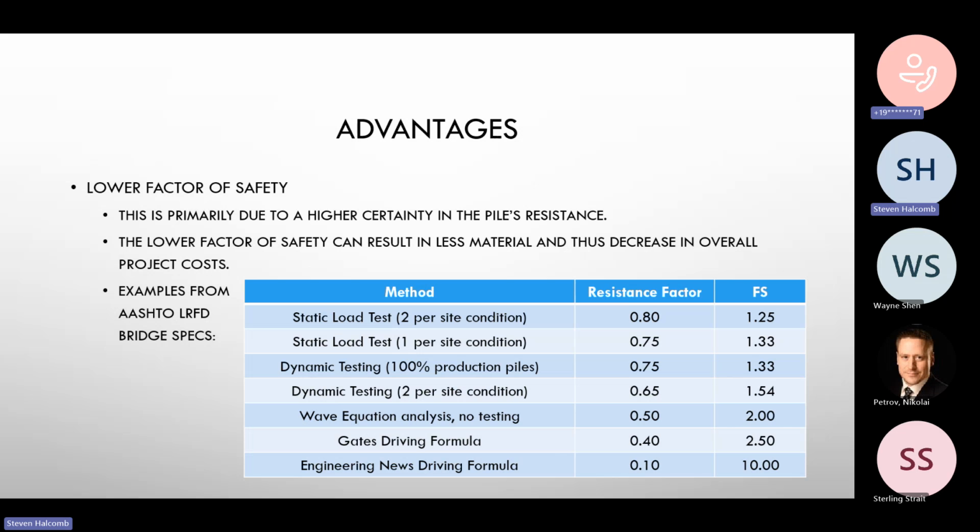Usually I mention this in my reports when I do deep foundations. I usually talk about the wave equation versus PDA. Most of the time when I've thrown out static load tests, nobody wants to do that, which is understandable. But occasionally it's required and beneficial. But usually it's a small percentage, like I said, and then you can use a little bit lower factor of safety.